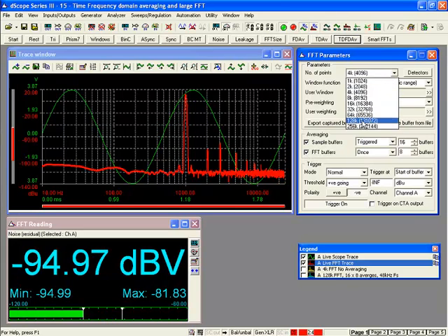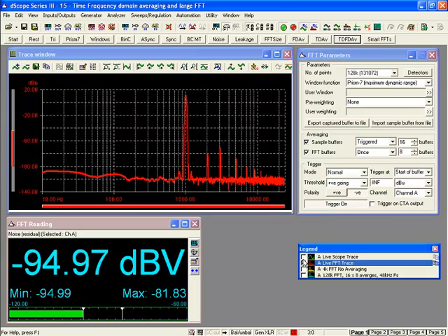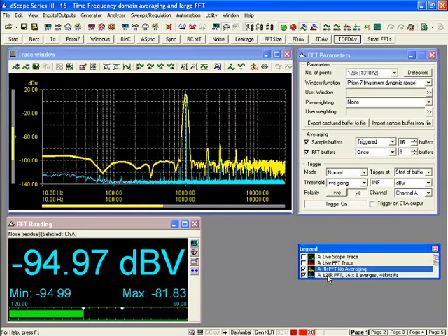And I've also chosen a very large FFT size, in this case 128K, and of course this took quite some time to execute, so I'll show you the measurements here. This was our original measurement in yellow, where we were struggling even to see the intermodulation products either side of the 1K tone here, and we were certainly struggling to see distortion products above about the 8th harmonic.